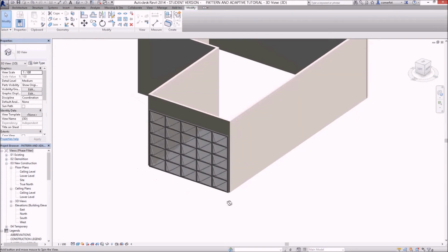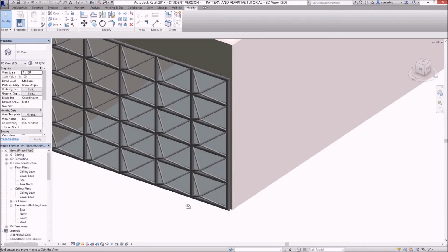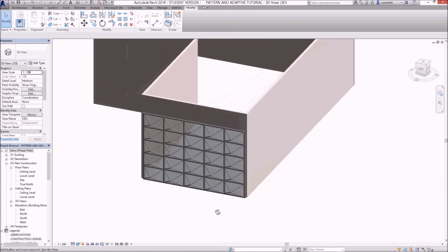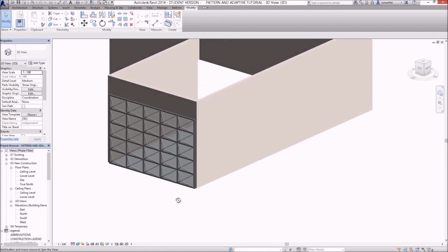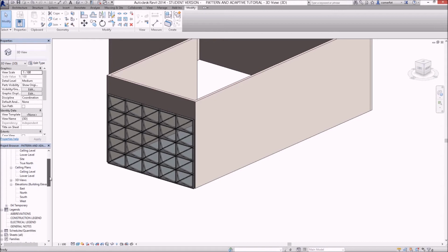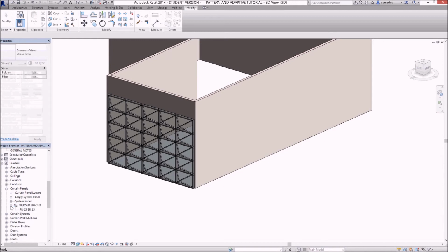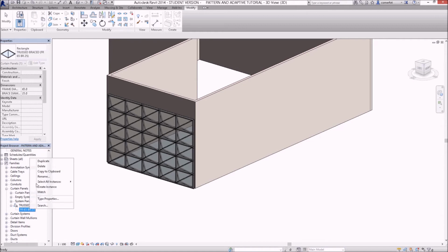So even with the mass off that we created all this geometry on, the actual geometry of that curtain wall panel still shows. Now I really probably wanted them to be all flipped around the other way, so I think the best way of doing that might be to turn the mass back on, show mass settings, so I can select the whole thing in one go, and I'm going to try and rotate this. Yeah, there you go, it'll seem to rotate. I'll probably have to rotate it and then put it back into position better later, but I'm just going to quickly try rotating. So I tried this before and type 180 and press enter. Well, there you go, it's established itself pointing back in the right direction.